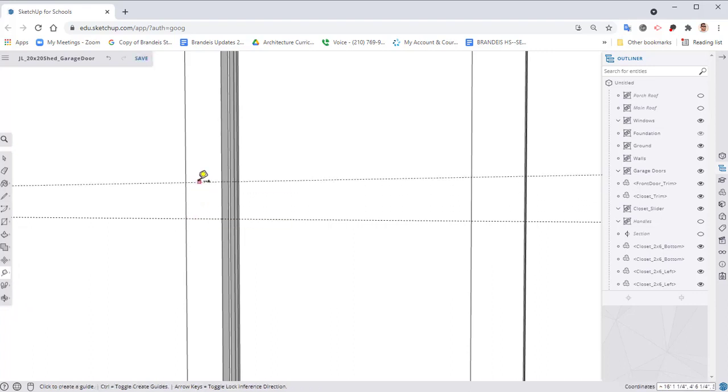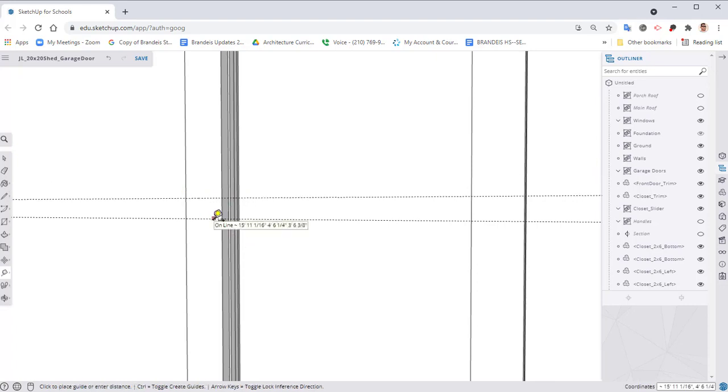So from that center point, we're going to go up 2.75, and we're going to go down 2.75. Making sure that your line when you're doing this is blue or whatever color you're going for. That way you know it's straight. The overall measurement should be our 5.5.